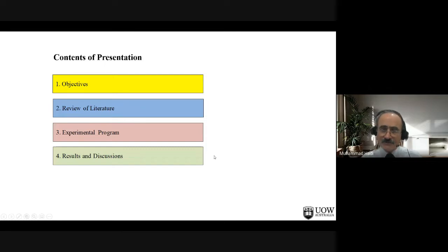The main thrust of the work of Qasim, or Professor Khan, was to use FRP tubes in concrete columns. So the main thrust is this. Why FRP? Because of corrosion. I told you we have a bridge. Whenever there is water, marine, salt, there may be corrosion. So this is the reason we are going to use different materials, in this case, FRP tube.